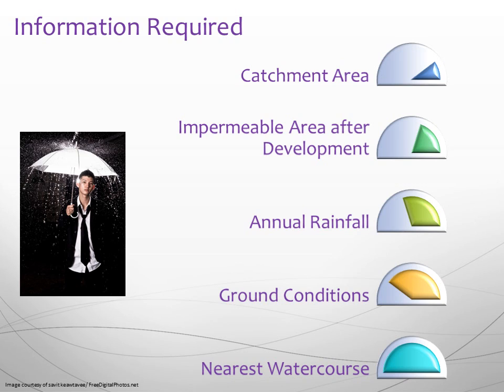The ground conditions can be determined from actual ground investigation on the site, and this will determine the ground percolation rate. Wallingford Hydro Solutions also produce soil survey maps giving details of the winter rainfall acceptance potential, from which the soil index can be calculated. The site topography, such as slope and any nearby watercourses, can be attained either from the site visit or from relevant ordnance survey maps. Other useful sources of information are Google online maps and in some cases historical maps of the area.